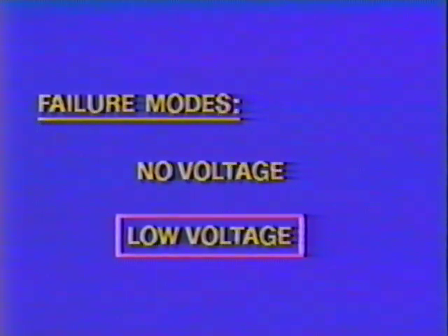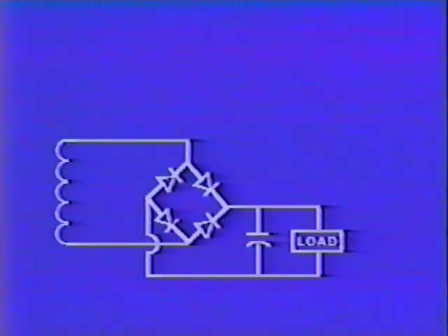This symptom is often observed in abnormal operation of the product. Video or audio noise, change in video size or shape, irregular or improper operation of the control section of the product may all result from low voltage output. Low voltage problems are often produced by a diode failure.